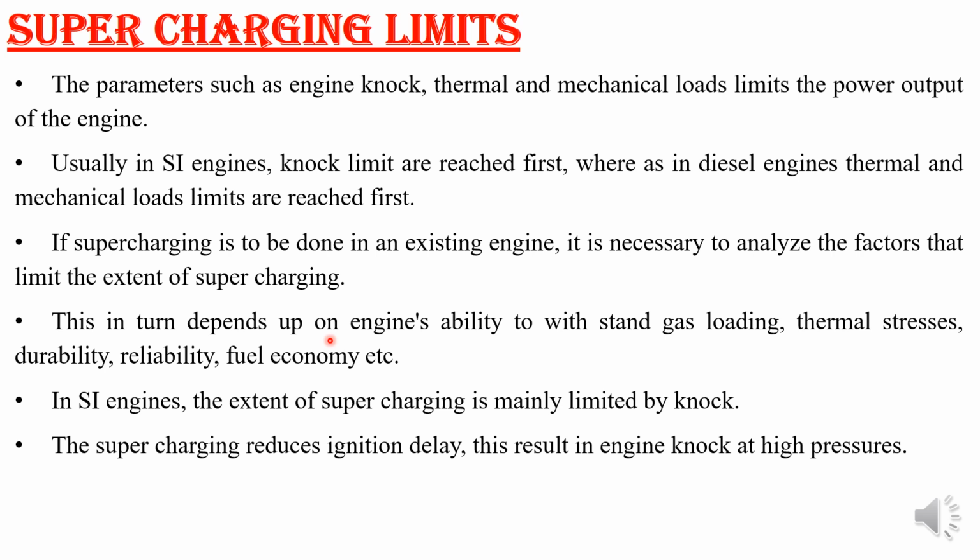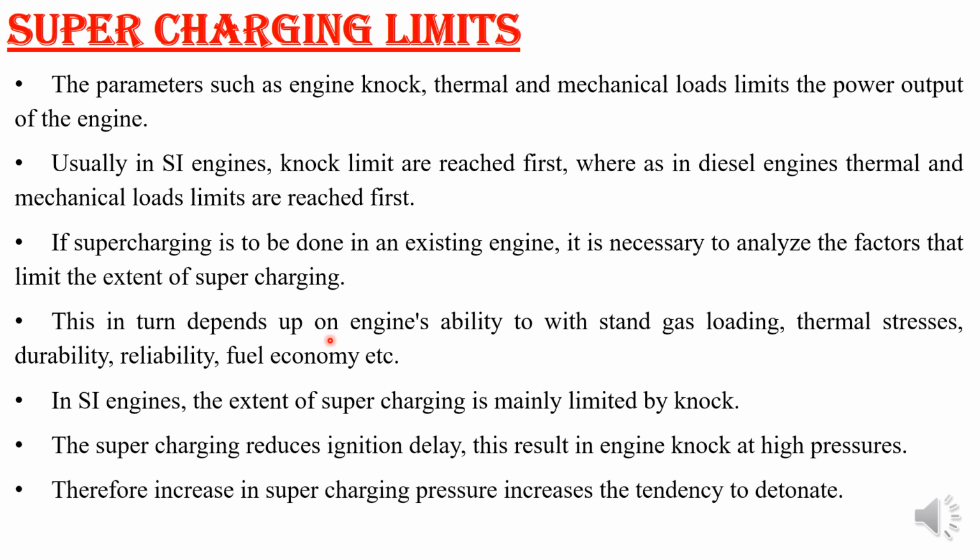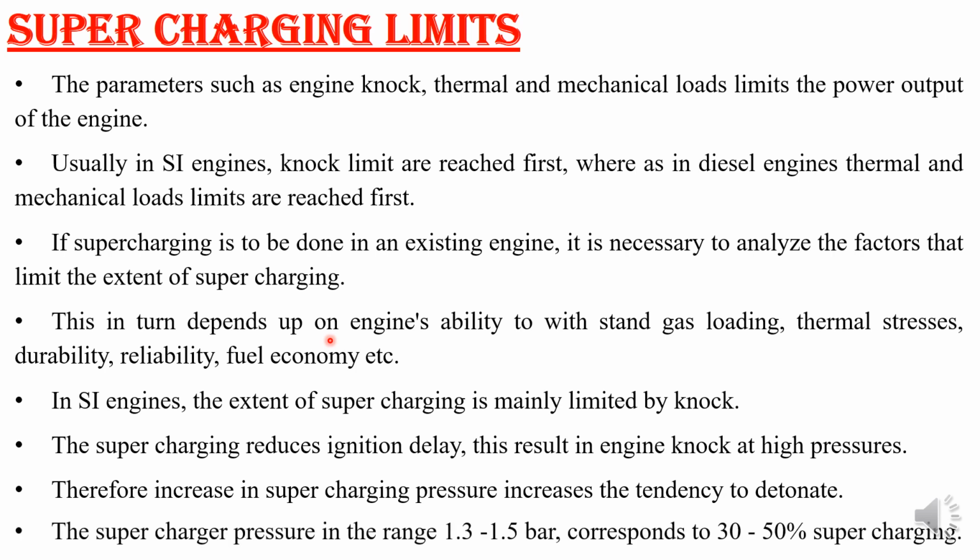Then knocking may come into the picture. So supercharging reduces that delay period, and it will result in engine knocking at high pressure. Increasing the supercharging pressure increases the tendency to knock. So the supercharger limit is 1.3 to 1.5 bar for an SI engine, corresponding to 30 to 50% supercharging. That is the limit we can go to for an SI engine, 1.3 to 1.5 bar.